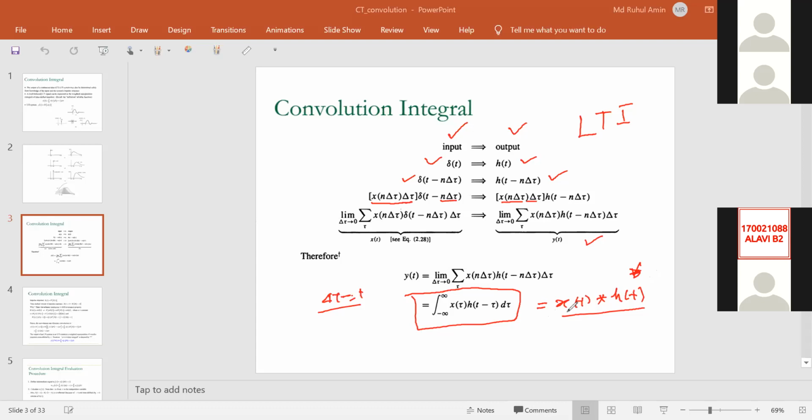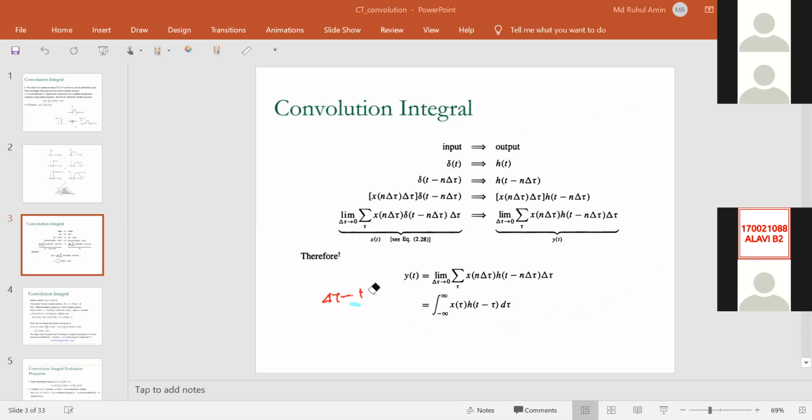So we'll be discussing how to determine the impulse response. Meanwhile, in your control engineering, you have already defined your transfer function concept. So if we can find the transfer function, then the Laplace inverse of the transfer function of a system is the impulse response that we discussed in the last class. But in time domain, by using differential equation solution, you can also find the impulse response. We will discuss later how to find the impulse response of a continuous time system.